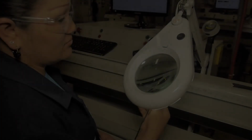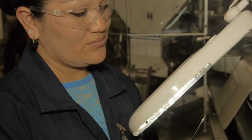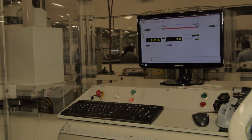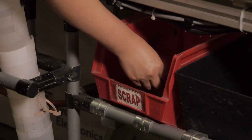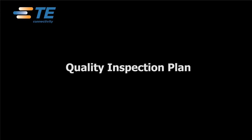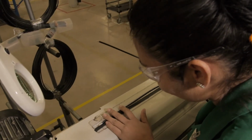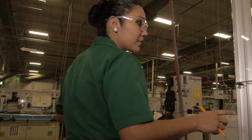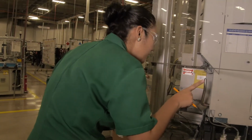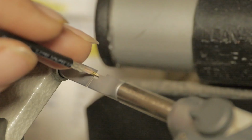Non-conforming material should be inspected by the operator. If excessive failures are found, the equipment should be stopped to investigate for potential root cause by the team. Non-conforming materials should be properly disposed in the scrap bin. The quality auditor will conduct checks per the quality inspection plan, which typically includes verifying length of the cable, verifying part number of the wire, verifying equipment setup, verifying crimp width, verifying crimp height.